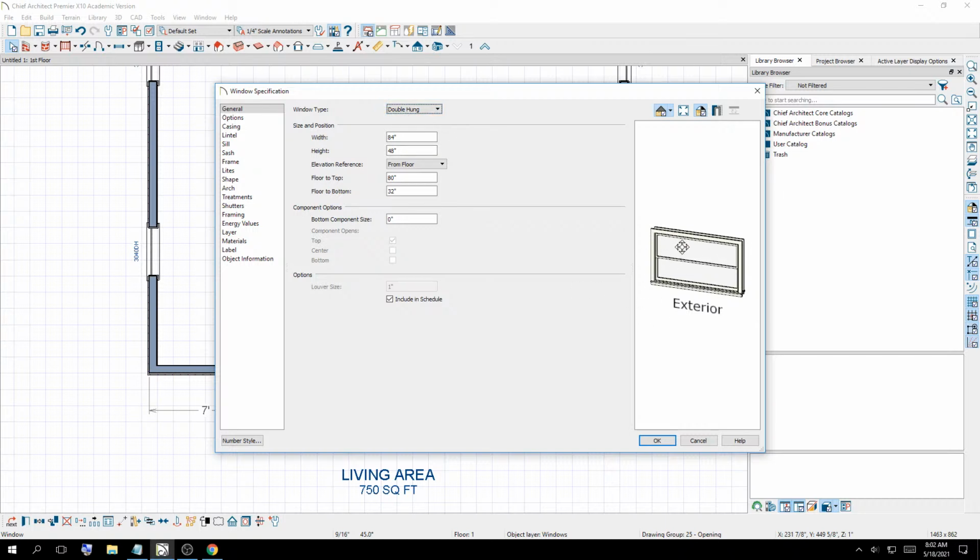You have your various panels here, your sash or window, they'll open and close, they're double hung. You could specifically say triple awning, if you needed a design that looked like this. I'm just going to press down, and you can go through the various options. Triple sliding, so the right and the left will slide. I believe the middle will be a fixed pane. This one's a single. Double awning, triple awning, single hopper, double hopper.